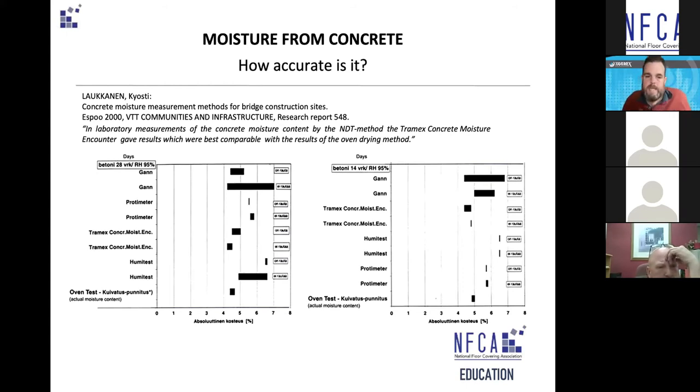Sometimes people say that you have to measure deep into the concrete, and that's fine. There's no harm in measuring deeper into the concrete. But the majority of your testing should be around the bond line, because that's where the issues occur. Provided you don't have a hydrostatic pressure issue, you're fine to just deal with the top 1 inch. There are cases where you can't drill, for example some residential flooring, where they won't allow you to drill into the concrete. It's just not an option. So the best you can do is measure from the surface down and then check the ambient conditions.